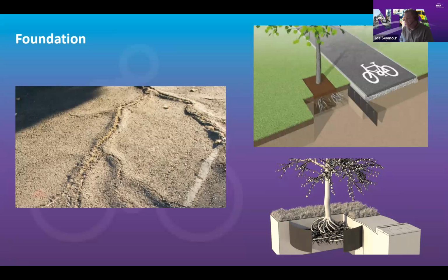So when developing the schemes, talk to the landscape architects, get them to specify trees that have limited impact. If we do know that the roots are going to be an issue from a particular tree, consider putting in root guards along next to the cycle track to prevent what's shown there in the image, which does cause cyclists to fall off their bikes or pedestrians to trip. And it's a constant problem around our cities at the moment.